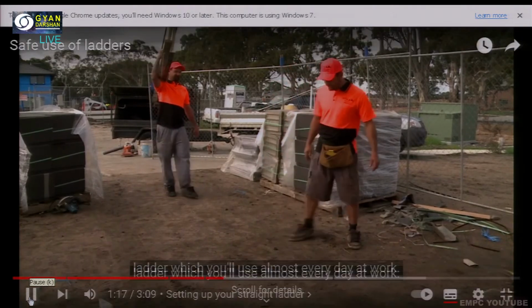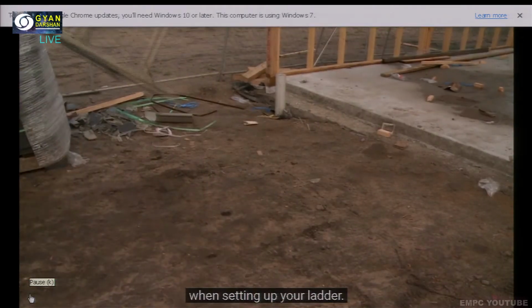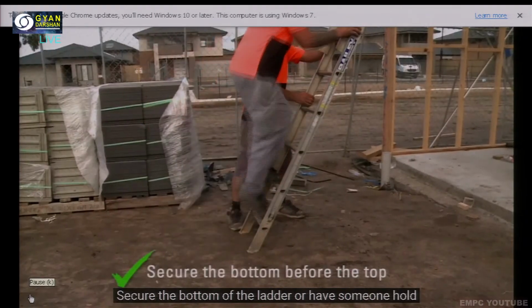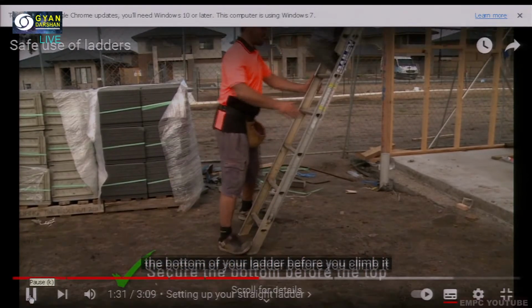Before we set up the ladder, we make sure that the site is good. We make sure the ground conditions are good for setting up the ladder. It has to be stable. No uneven grounds are permitted. And then usually if we are using a ladder which is not self-supporting, then we have someone supporting the person while climbing.